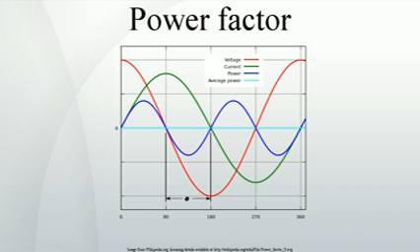A direct reading power factor meter can be made with a moving coil meter of the electrodynamic type, carrying two perpendicular coils on the moving part of the instrument. The field of the instrument is energized by the circuit current flow. The two moving coils, A and B, are connected in parallel with the circuit load. One coil, A, will be connected through a resistor and the second coil, B, through an inductor, so that the current in coil B is delayed with respect to current in A.